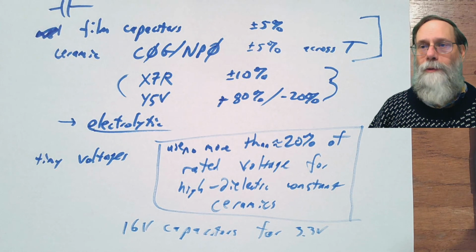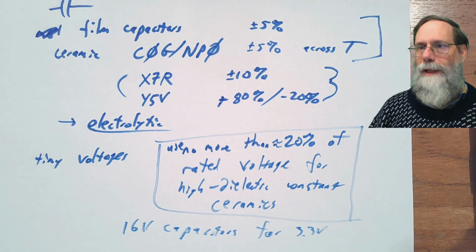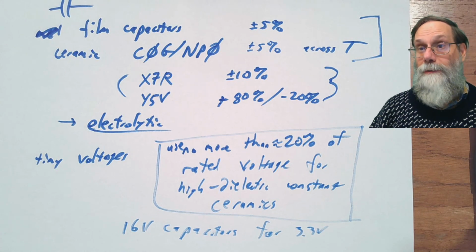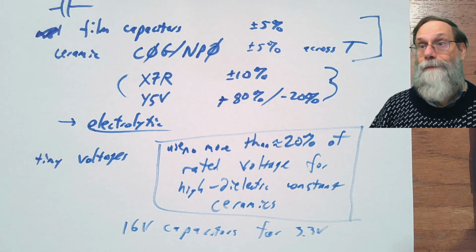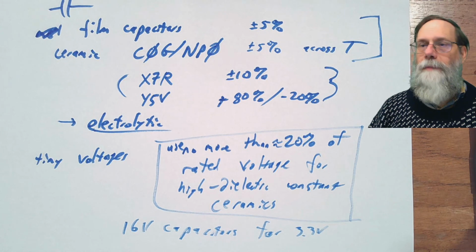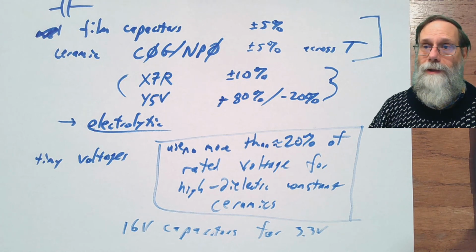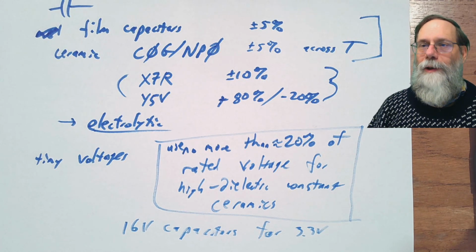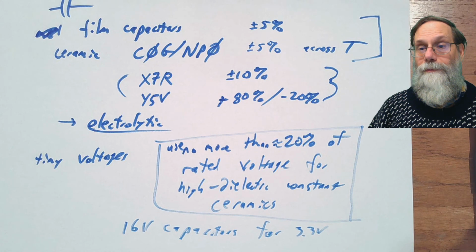And so put too much voltage across it and you break down the dielectric. So those tend to be something like 1.8 volts, but a farad or more. Special case of electrolytics. I've not had much use for the supercapacitors because I don't usually need very large capacitances at low voltages, but they exist.